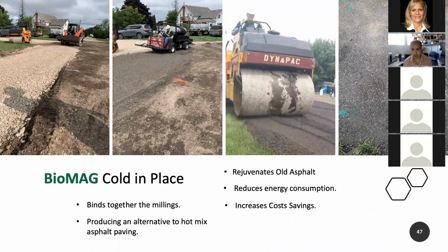And so you just drive over it a few times until you have a firm surface. And then the final finished pavement is on the right. And over a course of about a week, that pavement continues to harden and react until you get to a traffic bearing final product.